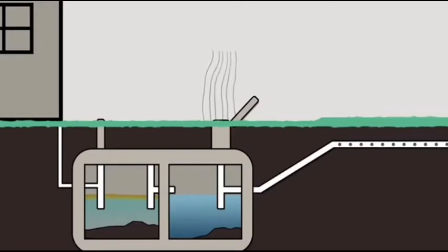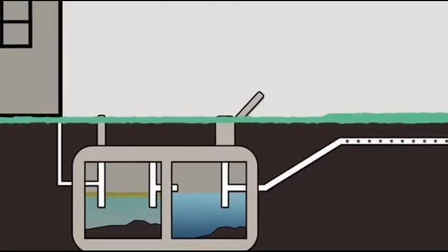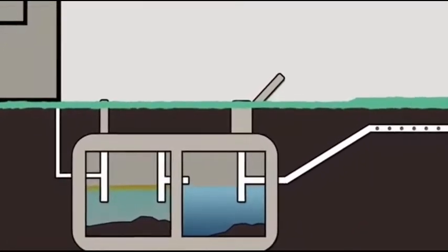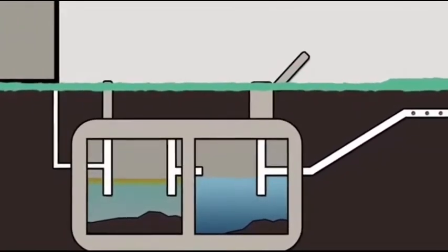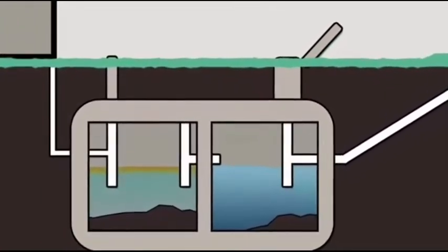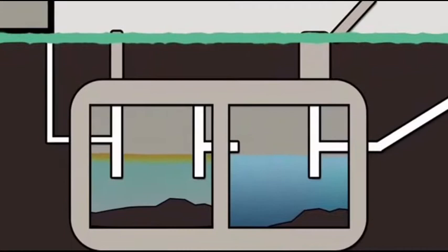Septic systems cannot dispose all of the material that enters the system. Solids that are not broken down by bacteria begin to accumulate in the septic tank and eventually need to be removed. The most common reason for system failure is not having these solids removed on a regular basis.